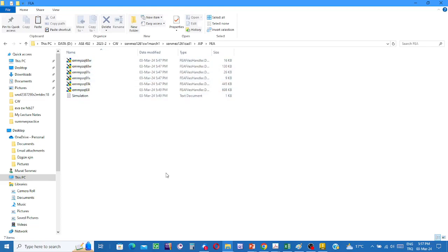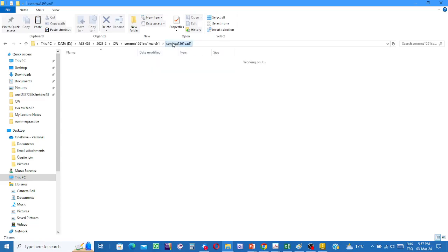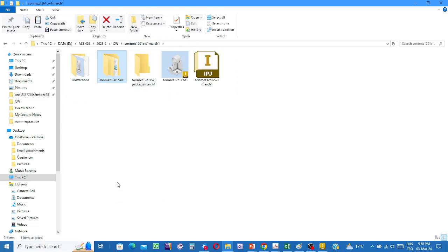Thanks to these files, Inventor, or the other person, when the solid model file is open, can see the results of the calculations. This folder must be associative. Okay, send not only the solid model but also this log folder, this data folder, to the other person. If you simply send the solid model and forget sending the calculation folder, the folder in which Inventor keeps the results of the calculation, the other person cannot see the results, cannot see the calculated values, and can only open the model.